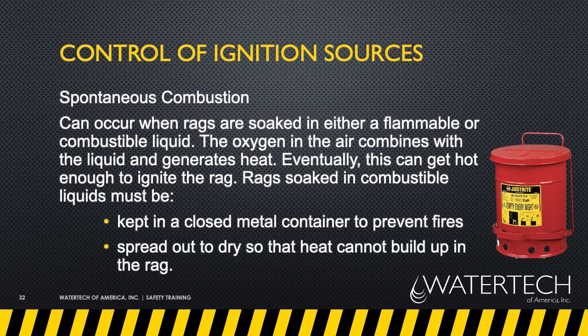Spontaneous combustion can occur when you have rags soaked in a flammable or combustible liquid. The oxygen in the air combines with the liquid and generates heat. Eventually, this can get hot enough to ignite the rag. Don't just toss rags soaked in combustible liquids into the garbage, or you are asking for trouble.